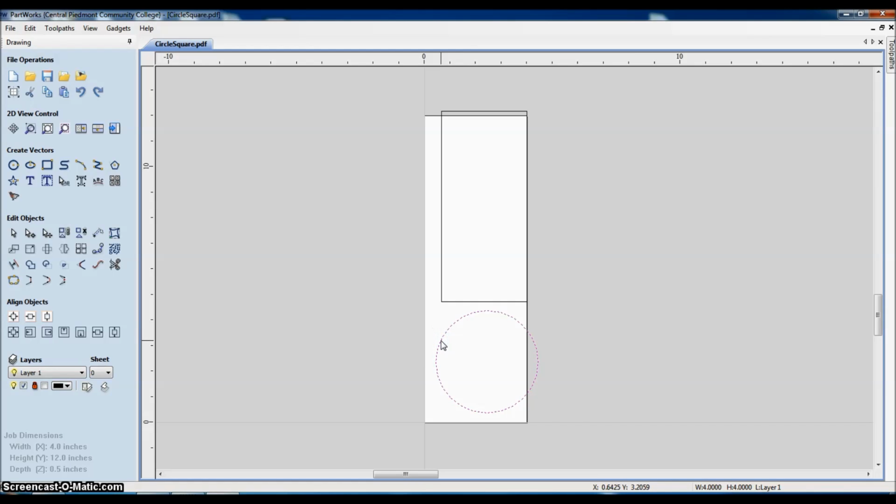If you don't do this, then the export will cut each segment all the way down. It takes like 4 different depth cuts, and then it will move to the next segment and do that again, and it takes forever. So just join them and you're good. I'm going to do the same thing with this rectangle up here.